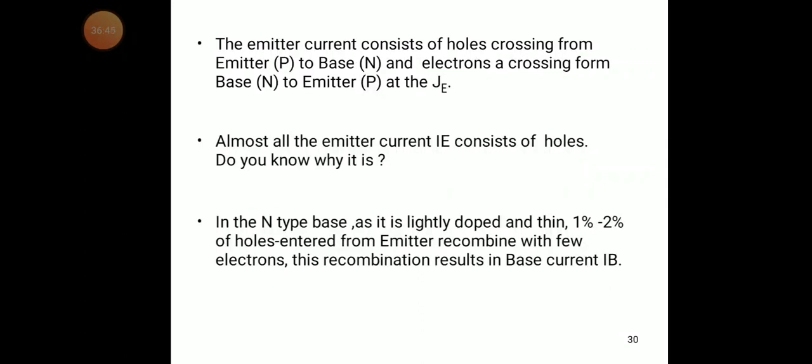In the N-type base, as it is lightly doped and thin, 1% to 2% of holes entered from the emitter recombine with few electrons.